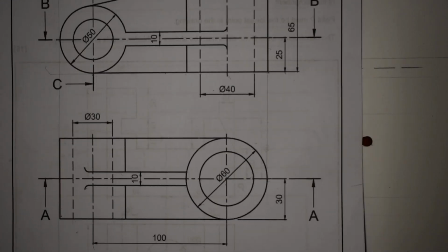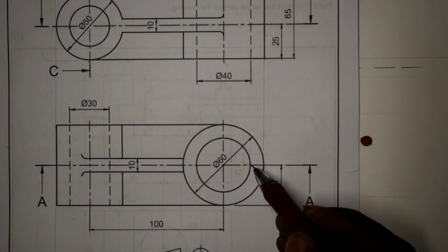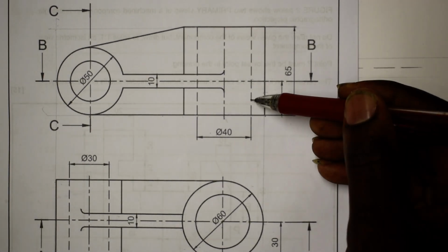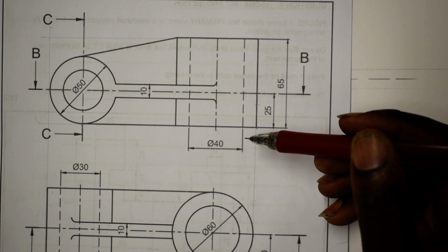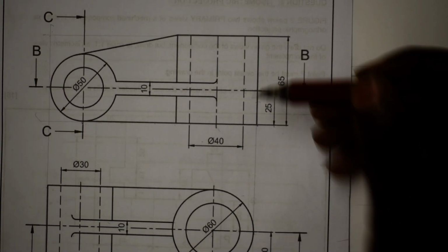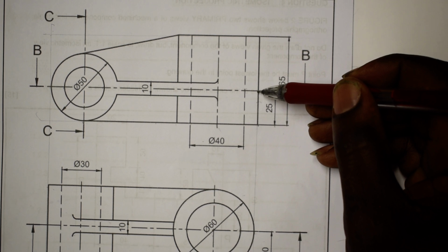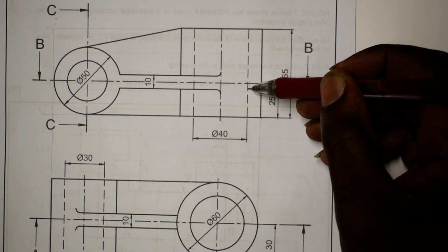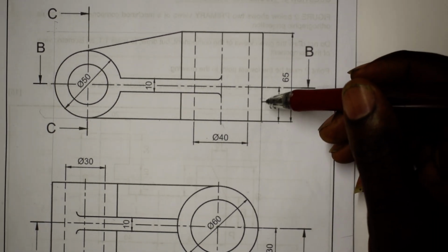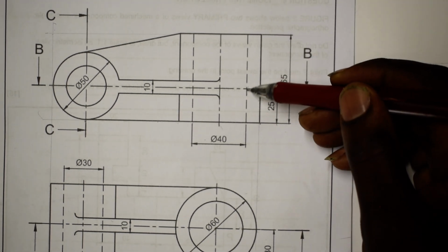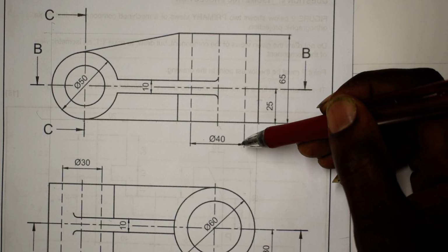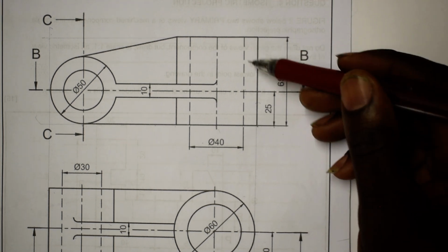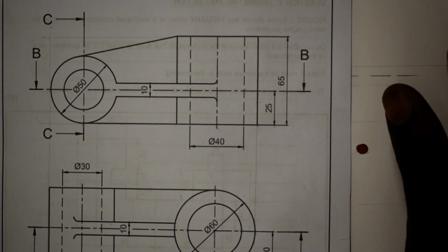Now if we are tracing the cutting plane of AA, so from there till they cut it, you understand, we do not have hatches from a solid line to a hidden line. Let me emphasize this point, I've been emphasizing in my previous videos that we do not have a situation whereby you hatch from a solid to a hidden line. No, it's absolutely not allowed. You must either change that hidden line to be dark, or you let it disappear, because sometimes hidden lines disappear. It's not like they always change to be solid. They only change to be solid if they were disturbed by the cutting plane.